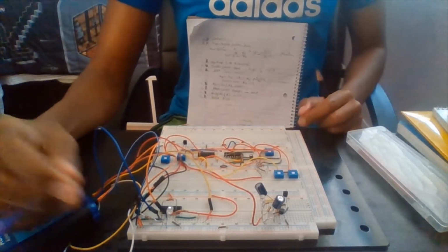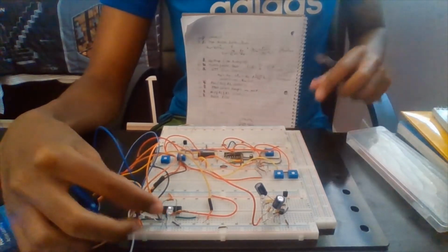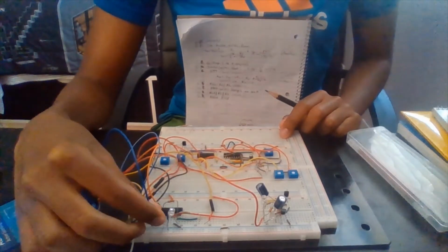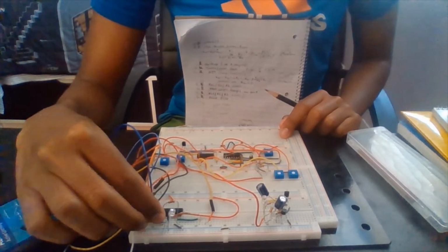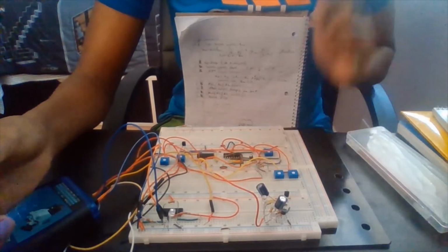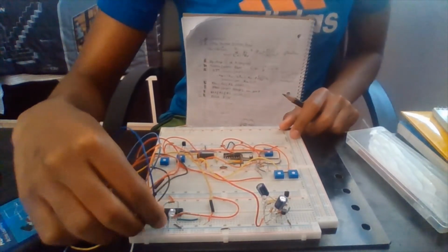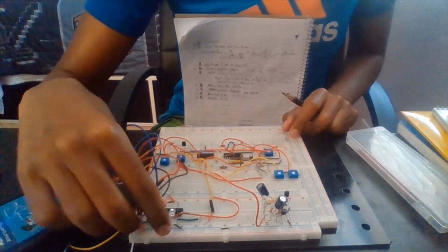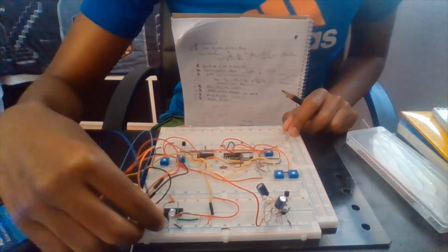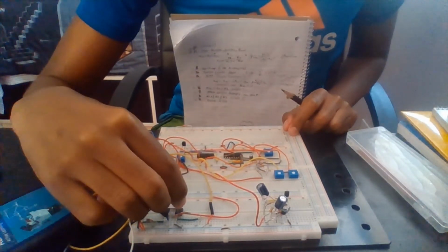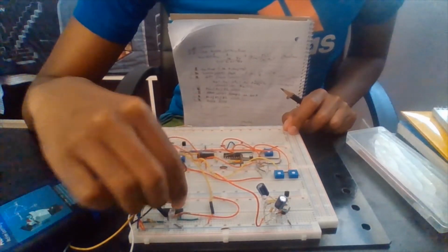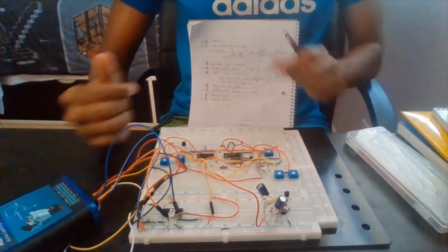All right, so that's the amplified voltage, but it's not quite necessary. I mean, we could still amplify more, but we also need to invert it, which is only possible through an inverting amplifier. So now we're going to move channel 1 over to this output. Actually no, let's keep channel 1 into the input, and let's move channel 2 into the output of this inverting amplifier. Alright, and now I'll be showing you a Scopy graph.